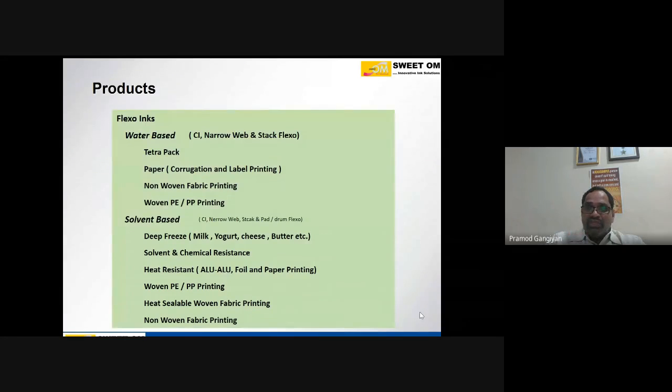Just to understand, this is based on carcinogenicity. All the solvents other than water are termed as carcinogenic, whether it is alcohol up to some extent, toluene, ketone, acetate or anything else, right? Water is not carcinogenic in that segment. That is why water as a solvent has a different category. So, water-based coatings as well as solvent-based coatings.